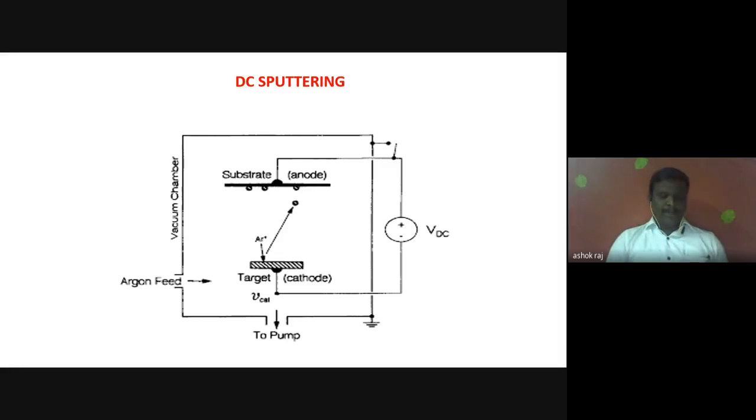During sputtering deposition, there is a chance of forming oxides due to the accumulation of oxides on erosion groove edges where the rate of sputtering is low. The sputtering yield increases with the help of three important parameters: we can increase the energy and the mass of the bombarding ions, and also decrease the angle of incidence on the target.